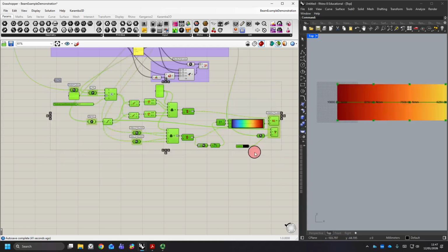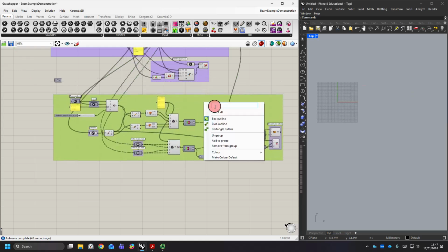So I'm just going to group all of these elements and I'll just pull them down a little bit, but I'll label this as contour plot for the axial force. So that's Fx if we're in the cross-section axis system, shear force Vz, or bending moment, and this is obviously the one that we have plotted, or bending moment My.